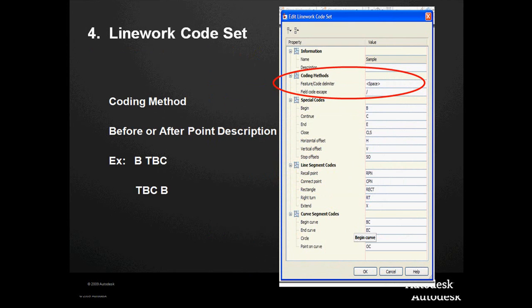As far as line work or field to finish, let me explain this a little bit. If you've done line work on the Civil 3D side or prior to that Land Desktop and prior to that Softdesk and DCA, our methodology for collecting lines has really stayed the same. We'd say B for begin, give it a figure name, and it would start drawing line work.